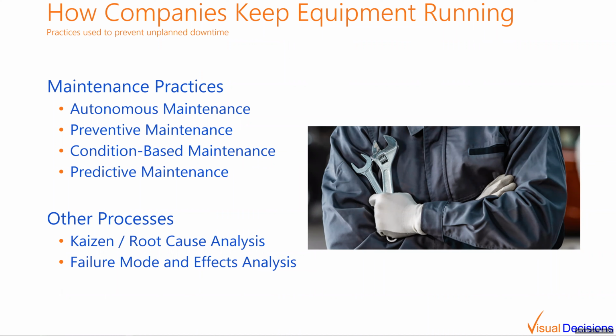I can also look at the mean time between same failures, which gives me an idea of the magnitude of the different types of problems for the machine. This metric is much more useful for measuring process improvement related to things that we've targeted at particular failure modes. So there are many different tools one can use to increase the time between failures.